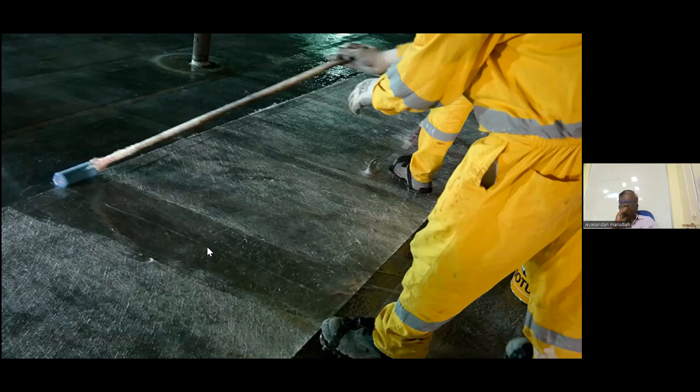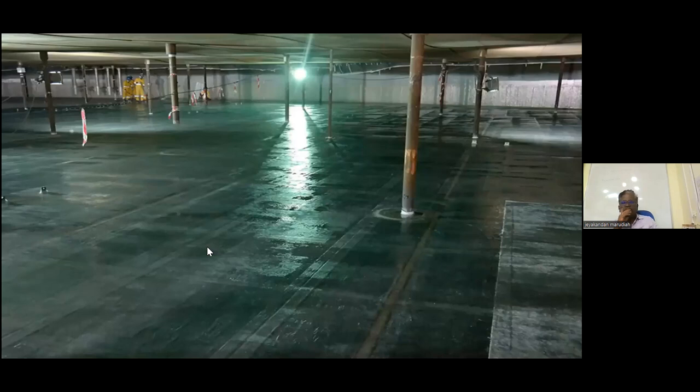This picture shows the fiberglass lining application in an external floating roof crude oil storage tank. In crude oil storage tanks, lining will be applied in the bottom and first shell course, because the crude oil contains highly corrosive water which contains hydrogen sulfide and other solid contaminants. Based on numerous applications over the decades, these systems have a proven history of successful performance.